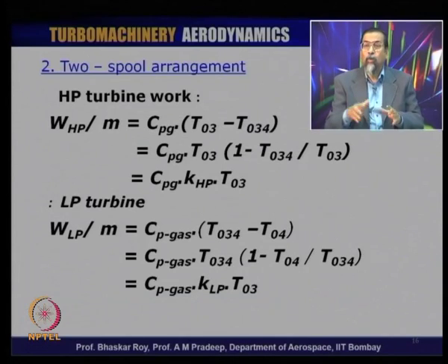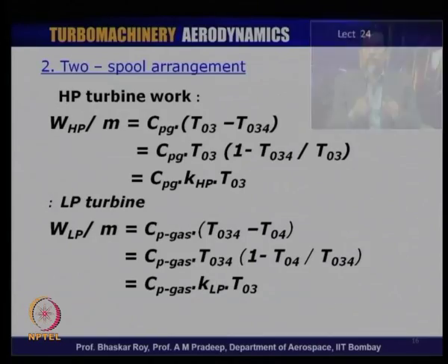From this matching, you can actually then figure out what are the matched values of compressor and turbine pressure ratios at that matched design point. So, that matched point is indeed the design point, and at that design point, you can find out what is the matched compression ratio and what is the matched turbine expansion ratio, for which the compressor LP HP and then turbine HP LP would have to be designed separately by the compressor designers and by the turbine designers. So, this is how the configuration is finally arrived at before the blade design is indeed taken up.